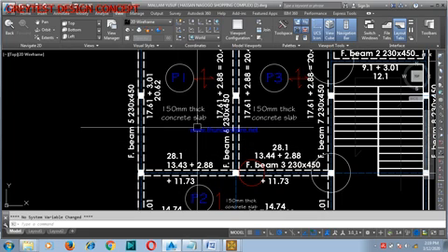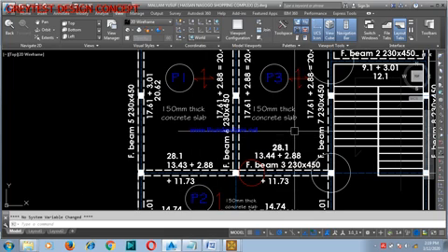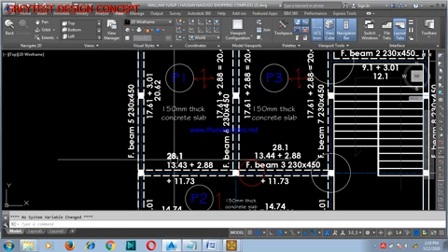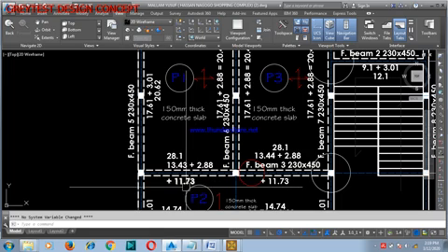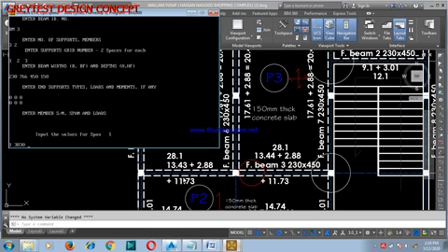You can see it's carrying from both sides, from panel 1 and panel 2, from panel 3 and panel 2. That of panel 2 is 11.73. When you sum everything, it gives you 28.1, so you type in 28.1. That is the load acting on that particular span.